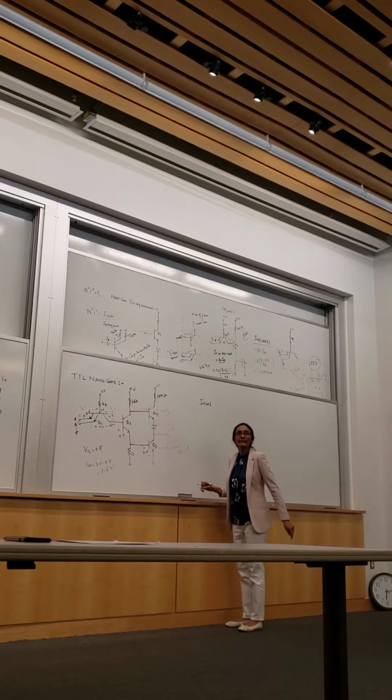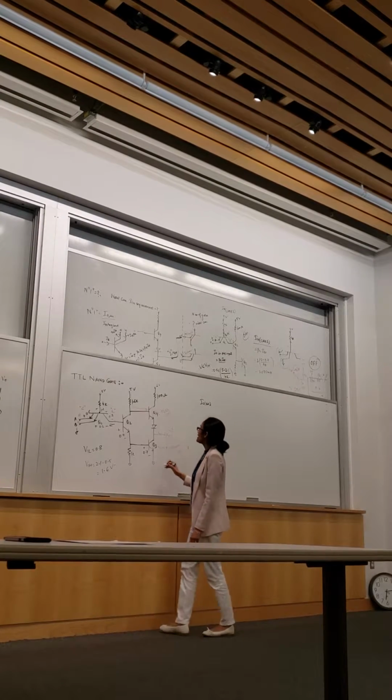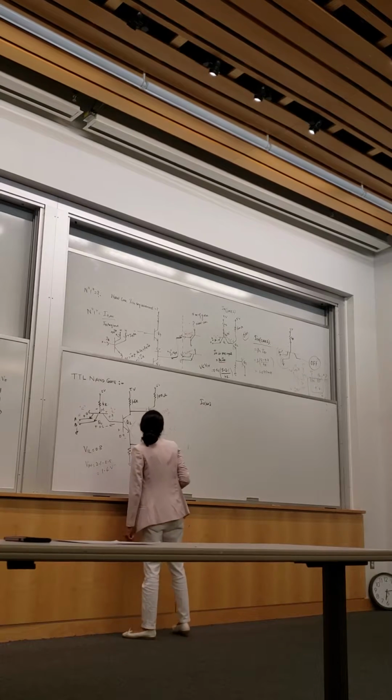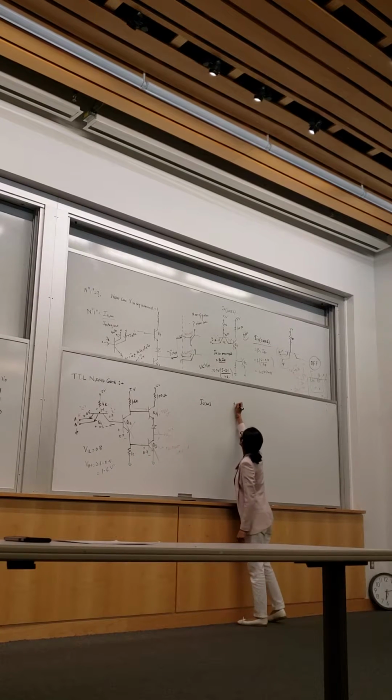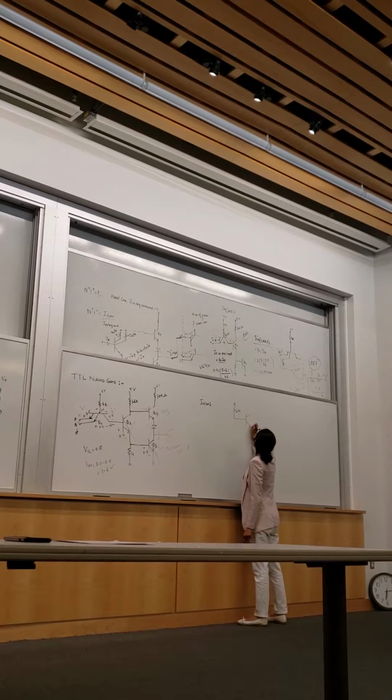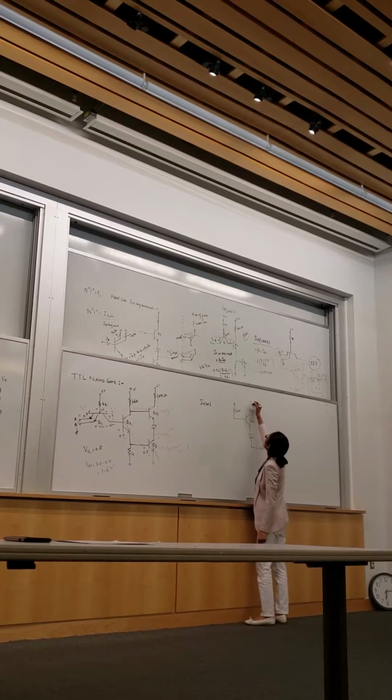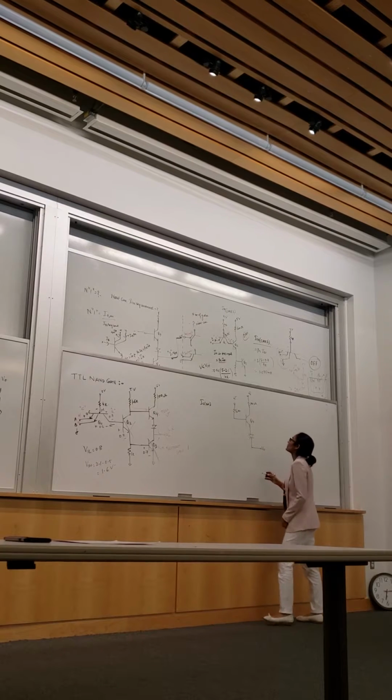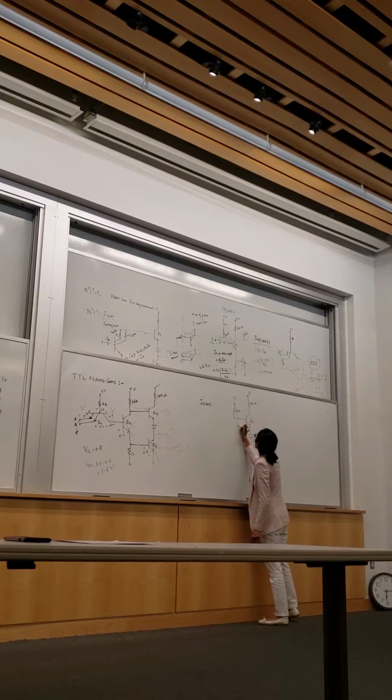For logic high, okay. Logic high means this is off, right? So redrawing the circuit, you're gonna get 1600, Q4, diode, this is V naught, 100 ohms, 5 volts, 5 volts. That's IB4, IC4, IE4.